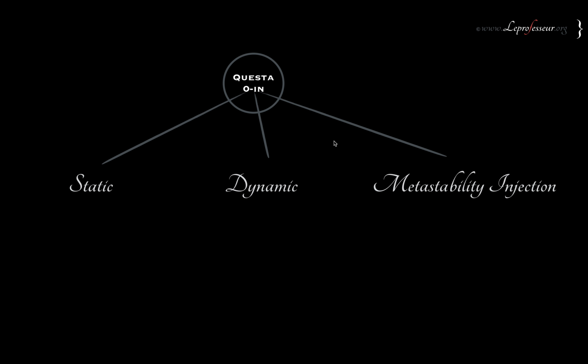But if there is an open loop solution where you just pass the signal from one clock domain to another clock domain, and you just rely on the signal being high for a certain clock duration, or, excuse me, a certain pulse width, then it becomes important to at least check the CDC verification in the dynamic mode, or in other words, generate the assertions and simulate your design with those assertions. So you might be surprised that you catch protocol violation errors.